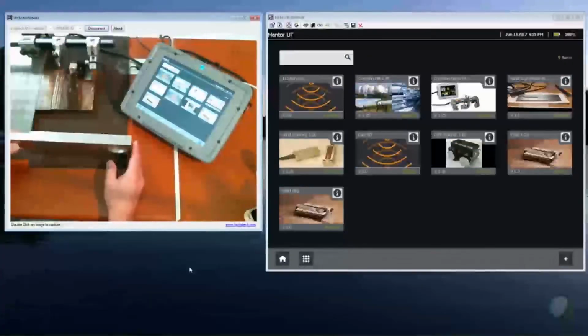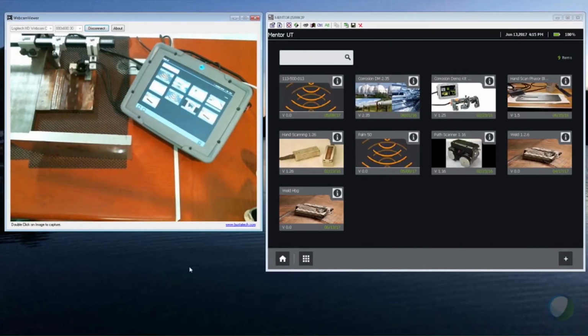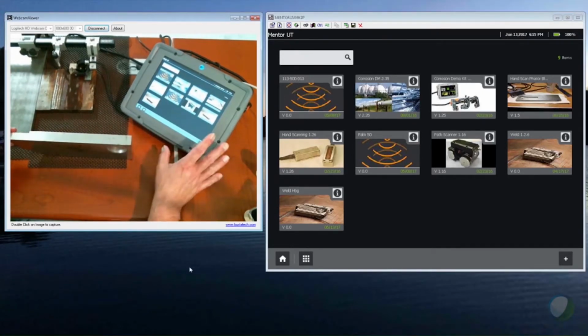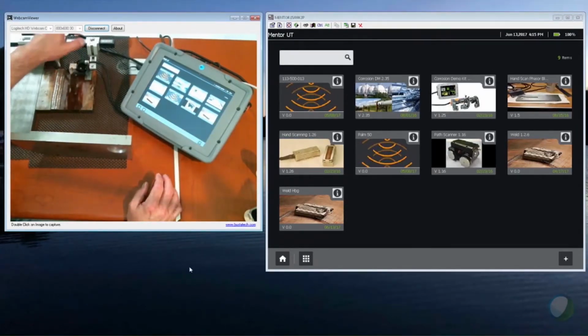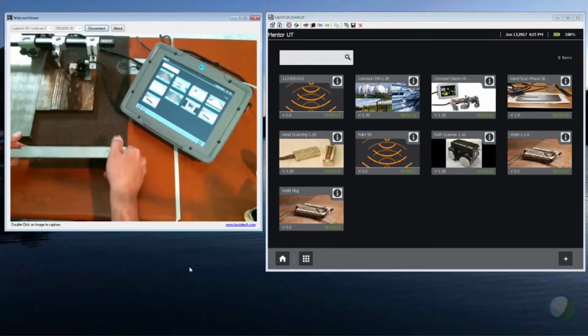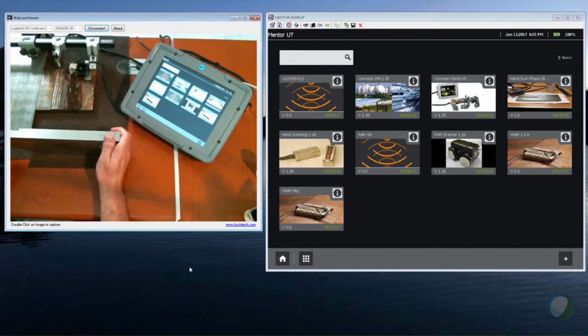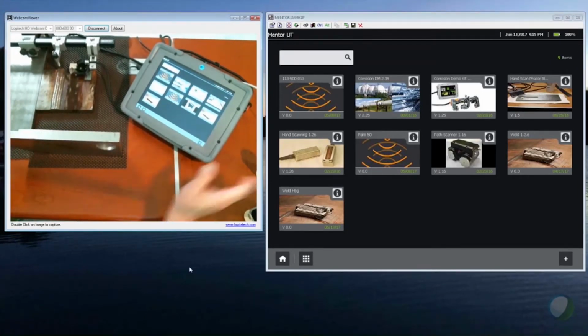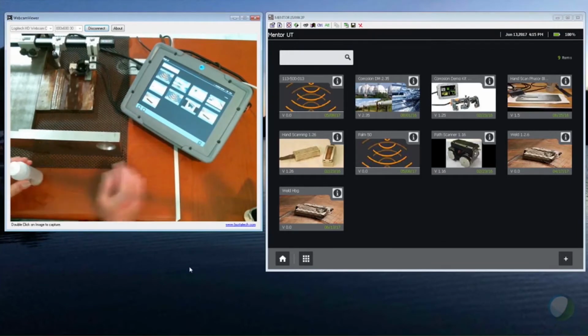All right, we have set up here on your screen. You can see on the left camera looking down on my equipment setup. I have my Mentor instrument, I have a scanner, probe, and wedge. I have the familiar IIW Type 2 block with 2 radii that we'll use in calibration in a little bit, and trusty bottle of coupling.